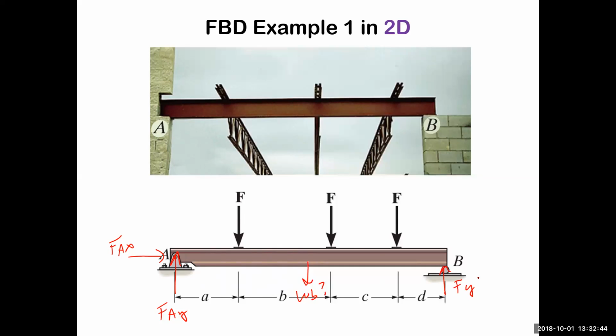Yeah, you could bring the wall into it, but in the idealized picture, it's this pin here, right? And that pin is going to resist translation either into the wall or out of the wall. The wall itself wouldn't prevent it from going this way, but you're right, it could prevent it from going into the wall. But there would probably be some bolts stuck there at A to keep that thing pinned on one side, and then it's allowed to shift on the other side.